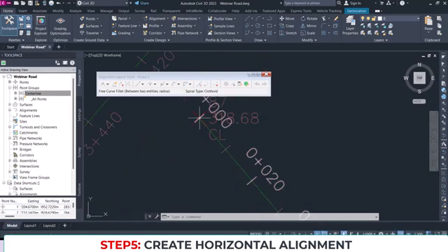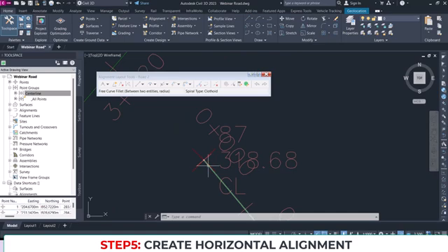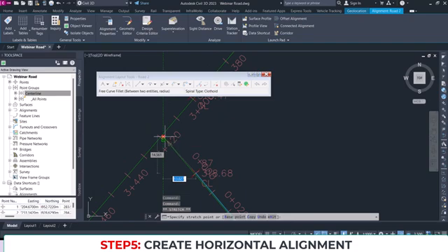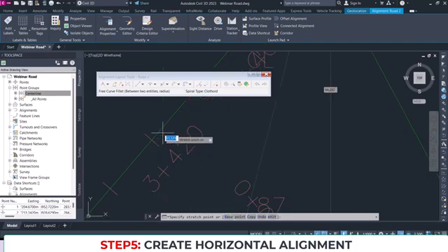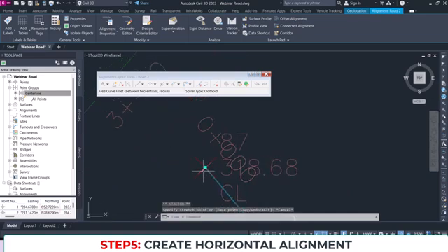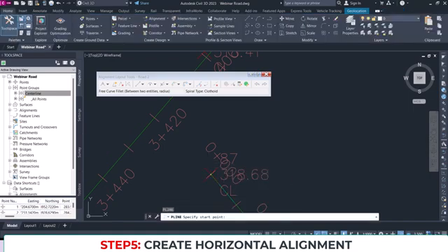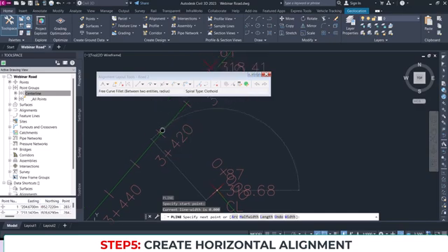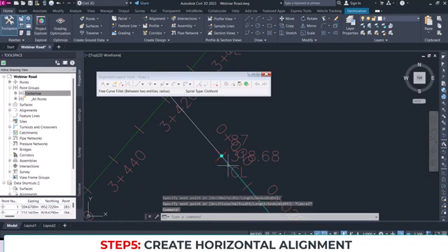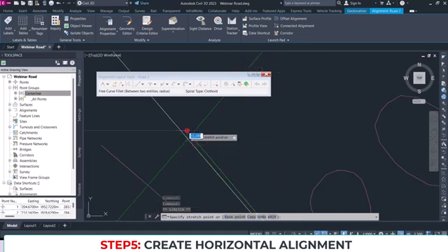So back to this place where it's supposed to intersect. You remember I told you we have to make this road intersect, so I just have to stretch this. I pick this up and then stretch it, making sure that I'm on the same line. If that is not working, there's a way I normally do it. I'll just draw a polyline, just PL, and then click from here, and allow it to intersect, then move and drop it somewhere, so that I'll have something to snap. Once I drag my alignment this time around, I can snap to where these two intersect.